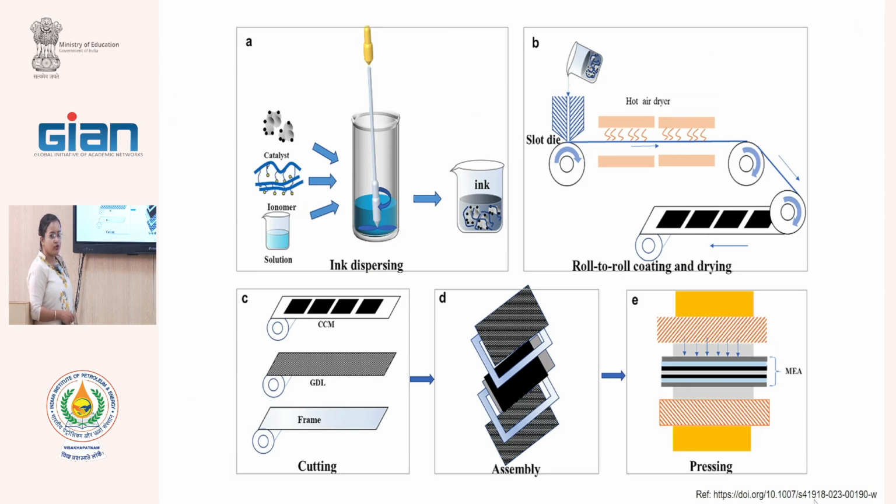Then they pour it in a die, a slot die. What is this slot die? A slot die is basically a big mechanical component where they have a very thin slit in between two metal plates. At the bottom of this metal plate they have a roller rolling. So imagine that a polymer film is put into this thin slit and a roller is rolling, then there will be a constant continuous coating onto the roller surface. Now they make a conveyor belt attached to this roller surface.